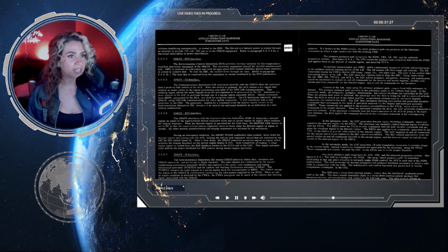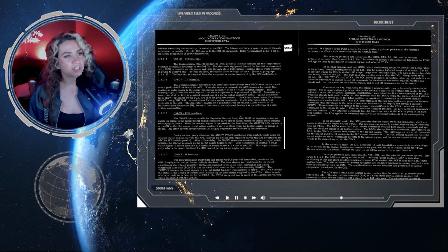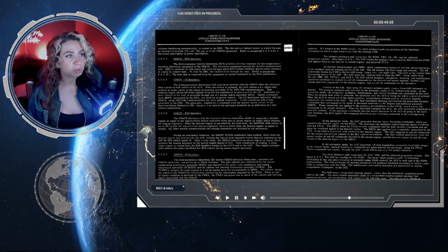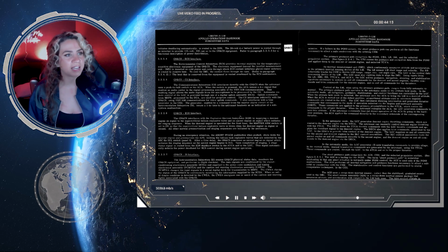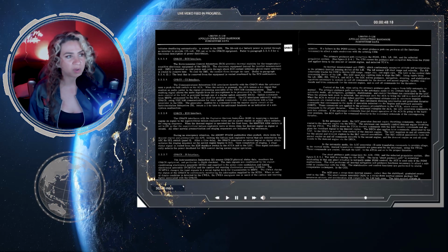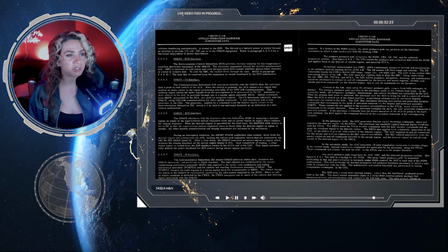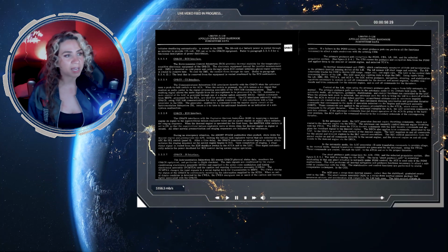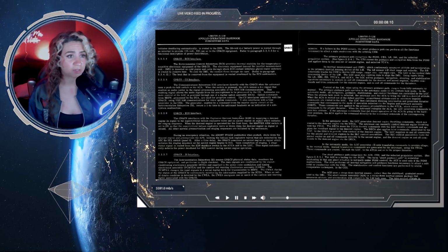The LGC is the central data processing device of the LM. The LGC uses star sighting data to align the IMU, using inputs from the LR, the IMU, the RR, the TTCA, and the ACA, and the LGC solves guidance, navigation, steering, and stabilization equations. The stabilization equations are necessary to initiate on and off commands for the descent and ascent engines, throttle commands, and trim commands for the descent engine, and on and off commands for the thrusters.